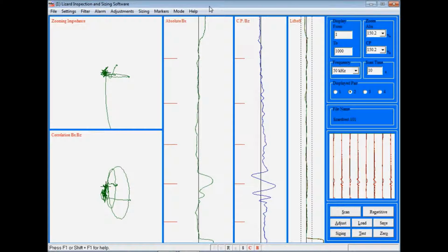Okay, we've now got a scan of an unknown plate, a full penetration butt weld. We use the repetitive function to quickly identify an area of interest for us to look at. Then we performed the scan and put these marker points in as simple strikes across the data.